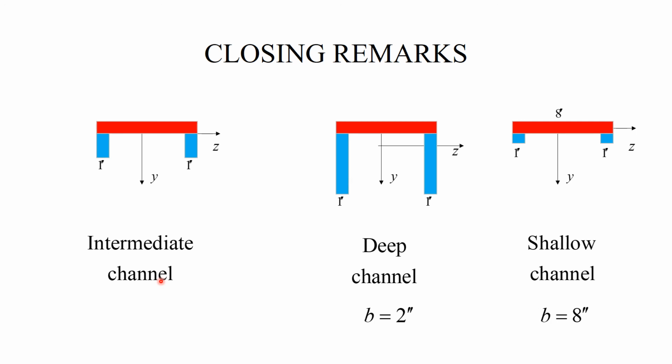We're doing a conservative estimate, but the story becomes a bit tricky, because we really cannot decide definitively whether it's 2 or 8. And so in these cases, it's a good idea to say maybe we need a more detailed analysis for this cross section to figure out what is going on with the shear stresses at the interface between the webs and the flange.